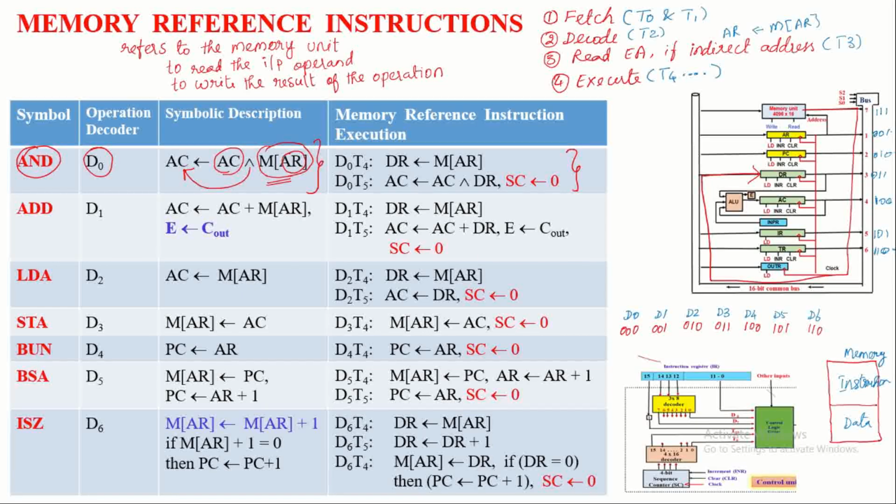The operand value is read from the memory unit whose address is pointed by the address register, and loaded into the data register. To achieve this transfer, the control unit has to set the selection signal values to 111 and activate the read signal of the memory unit. And to receive the data, the load signal of the data register must be enabled.